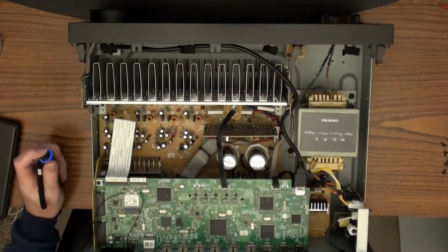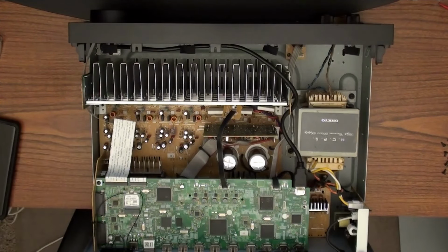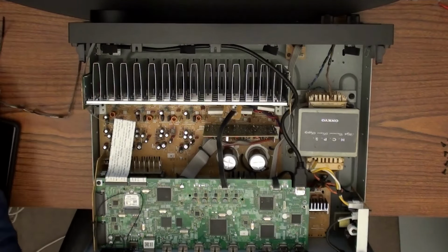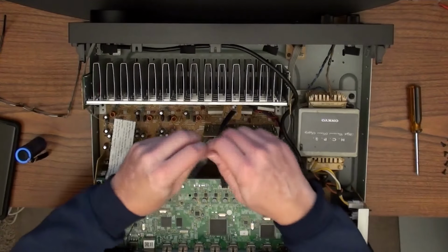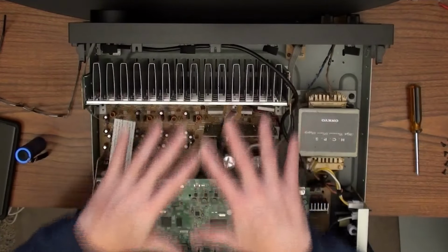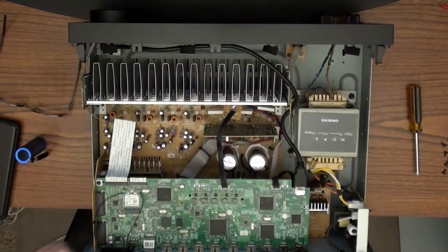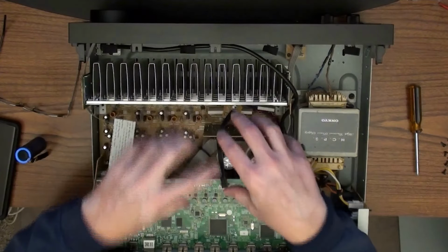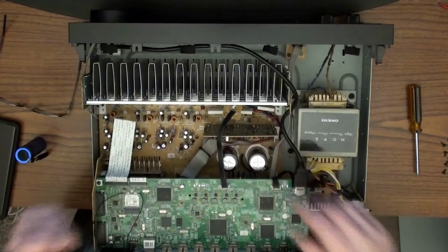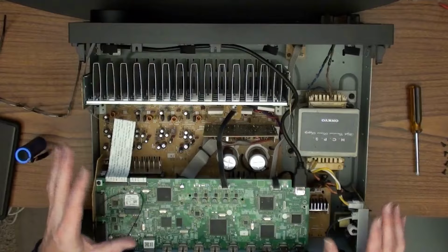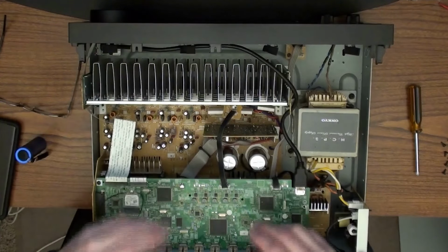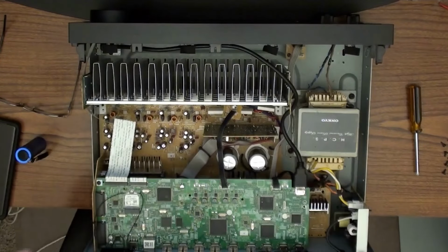So all those wire fibers could be causing the problem with this amp. So that's why it's very important not to do any twisting of wires or anything over the top of your amps, because you don't want them to fall down in the holes and land on the circuit board down here, because then this is the kind of stuff that happens. But like I said, I'm not guaranteeing that that's the issue right now, but from what I see, that definitely